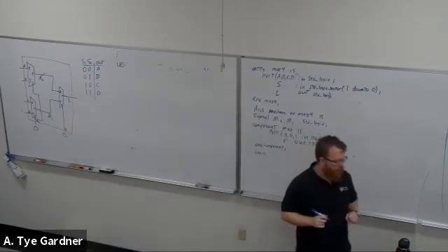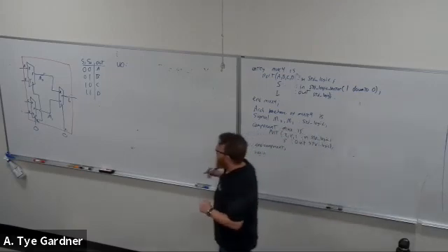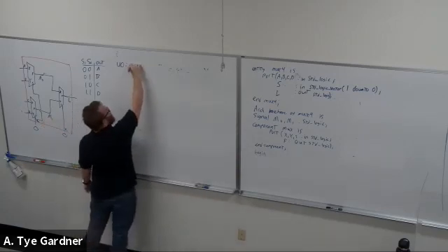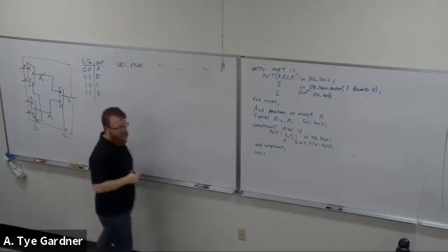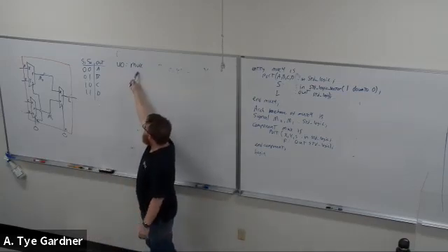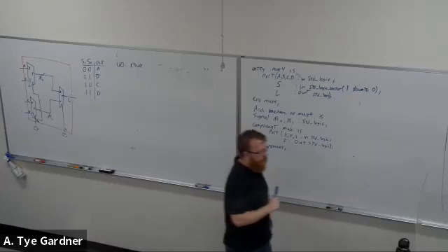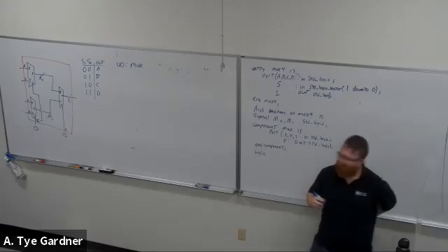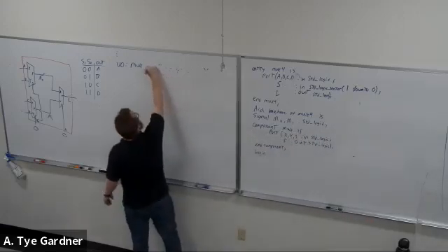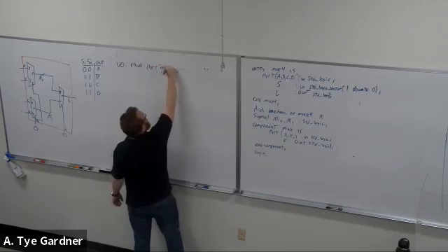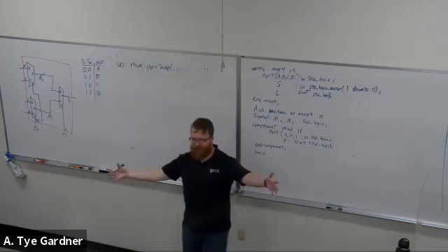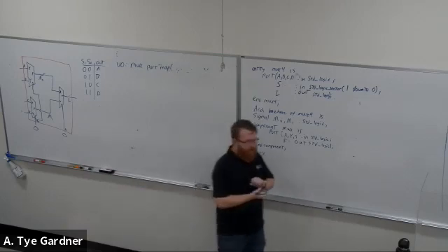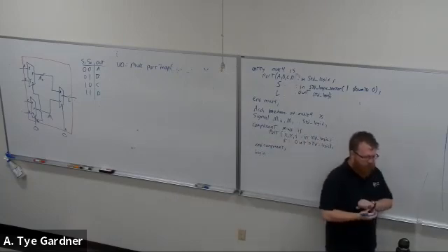Okay, and then once I do that, I have to tell what am I naming that? Well, I'm naming mux. Remember, I called these components muxes. Mux. That's what this component is. So I have a component of a mux named U0. Now I need to tell it how those ports are connected. Okay, and that's just as simple as giving it what is called a port map. This is how the ports are mapped. Where do they go, right? This port map is a description of where the ports go.